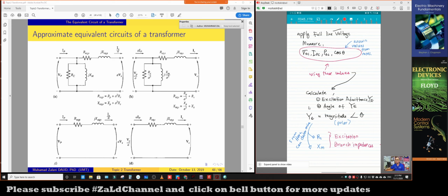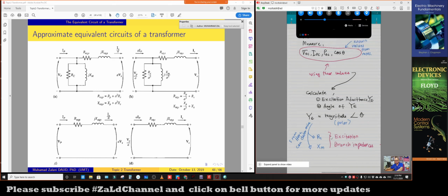All right. So our target for doing the open circuit test is to determine YE and also the angle of YE, so that we can represent YE in terms of its magnitude and angle. This is the polar form of YE. After we calculate YE, we get its value in terms of magnitude and angle. From there, as we have learned in our previous session, we can transform the polar form into the rectangular form.